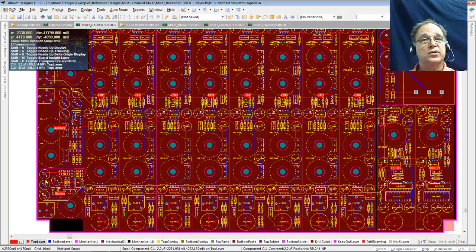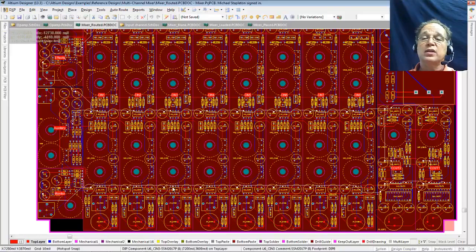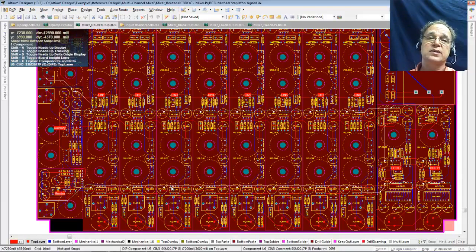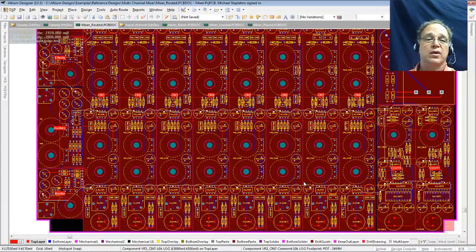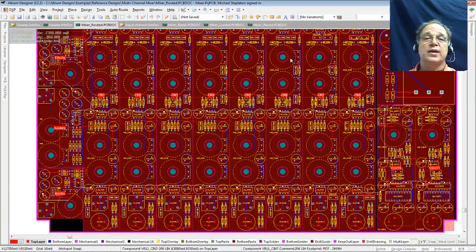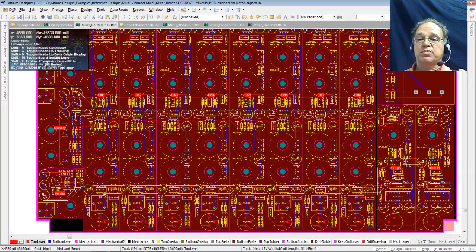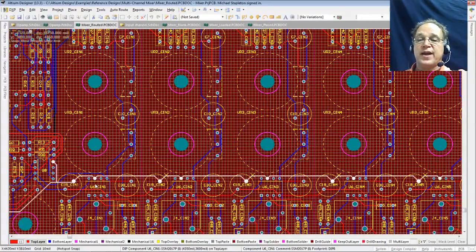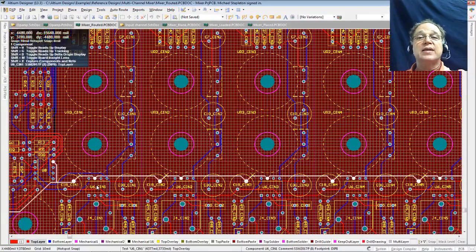Now remember, Ohm's law works for megohms. It also works for milliohms. When I look at this long, thin little piece of copper wire, it has a DC resistance. As I draw current, the farther along I go, the lower my voltage will drop. As well, that's about 3 feet or so of trace, so I'm going to have some inductance. So way at the end, down here, when this little active part decides it needs a current pulse to do its job, maybe there's a very fast signal coming in, I'm going to have too much inductance to maintain my supply voltage here. I'll have a drop in the voltage.